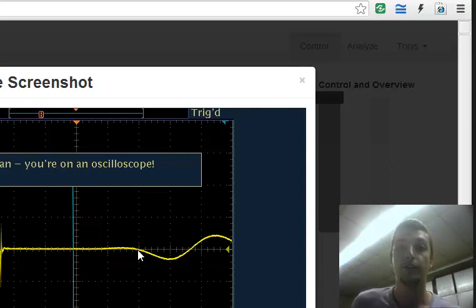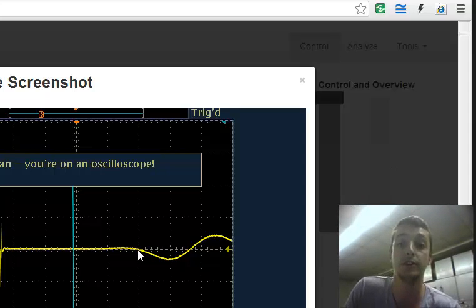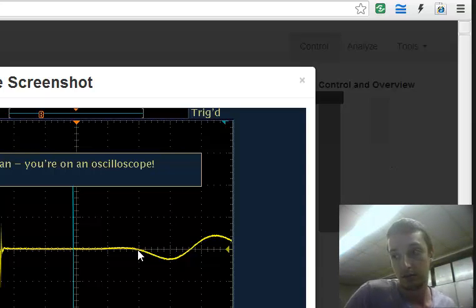So according to Professor Coutinho, or Dr. Coutinho's research, which is pretty much what this is based off of, you can calculate the modulus of elasticity and the density and the shear modulus just by getting the time of flight for each of the two sets of transducers.